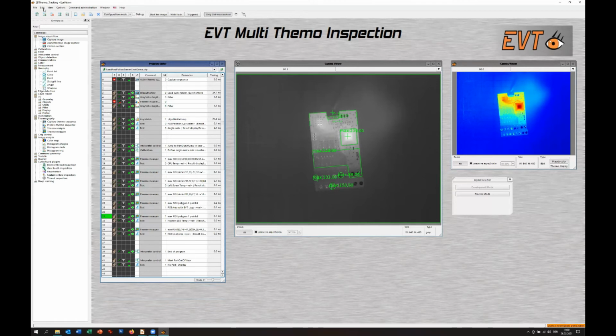So you can also, this is a single step. As long as we are in operation mode, and single step is also operation mode, you can stop the execution, then the program counter will go back. Or you can also say, I want to only execute these 5 commands for whatever reason, then you can use this one. Then it executes exactly these 5 commands, and the program counter is on the next position. So this is really comfortable and really nice for programming.